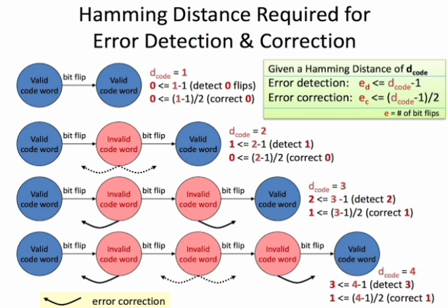There is another way of expressing the relationship between the message bits and the parity bits of a linear block code. H bar equal to [P bar transpose : I_(n minus k)]. H bar G bar transpose equal to [P bar transpose : I_(n minus k)] times [I_k : P bar] transposed, and so on, which gives P bar transpose plus P bar transpose, that is nothing but 0. So P bar transpose plus P bar transpose is 0. H bar G bar transpose equals 0. H bar G bar transpose whole transpose equals 0. G bar H bar transpose equals 0.